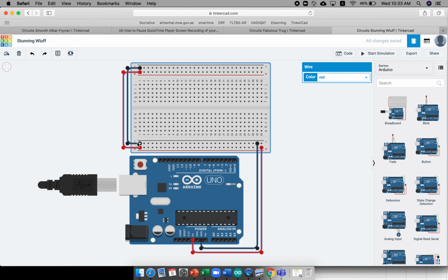So it's all connected in red to 5 volt when required. And again, let's go here with black. All this line is ground and all this is 5 volt. Why do we need to make this? It's to have tidy and neat connections. Not every time we need ground we come here, and not every time we need 5 volt we come here. Let's remember also that in the breadboard, every 5 points in a row are considered as 1 point.